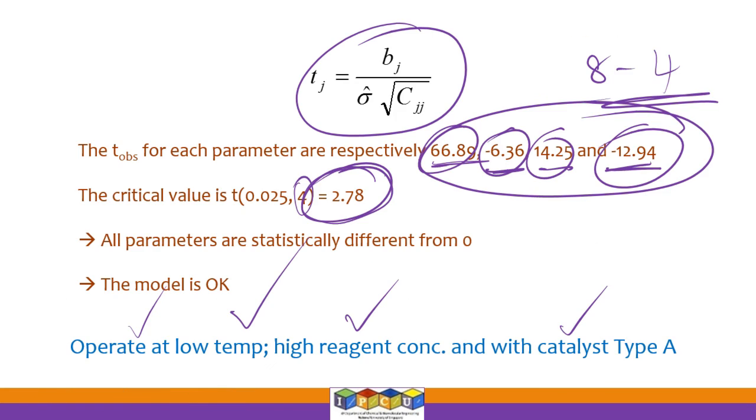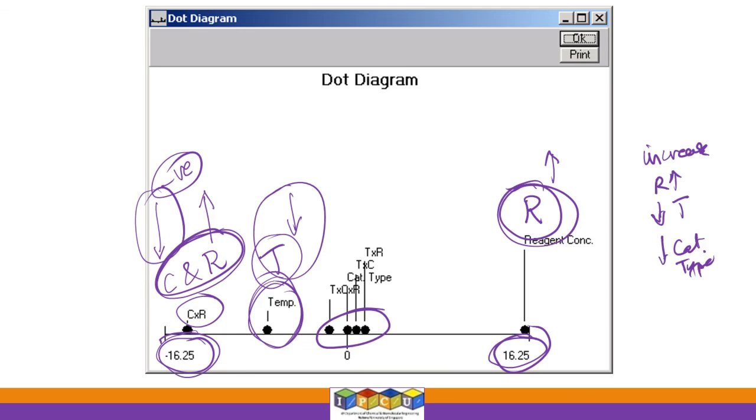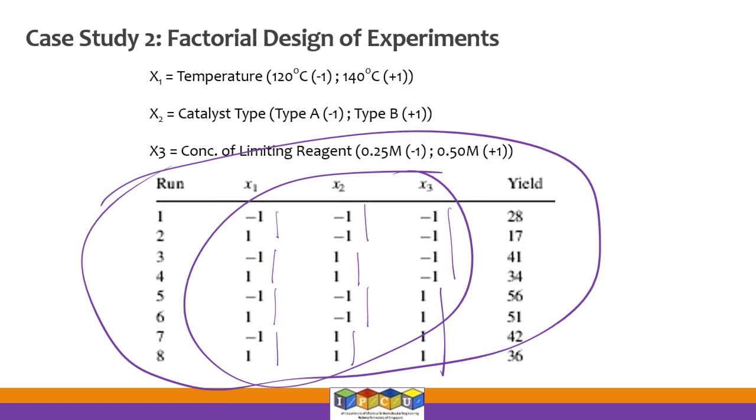Let's say even if you get a value like 55, let us see whether it has any benefit. We have gotten 55 before, 56 before, but the model tells you that you can go up to 62. So even if you get a value like 59, using those settings for x1, x2, x3 that the optimizer told us, we would be much better off. A 3% yield can mean several hundreds of thousands of dollars in annual savings, depending on the material being produced.